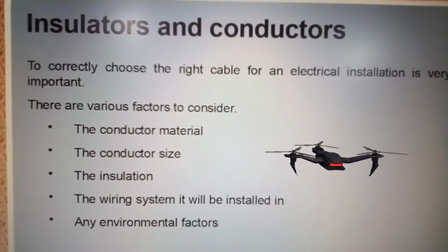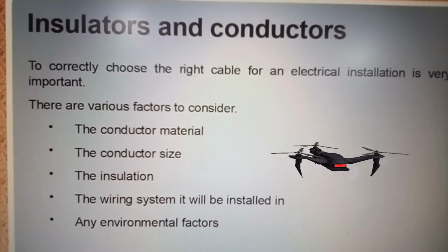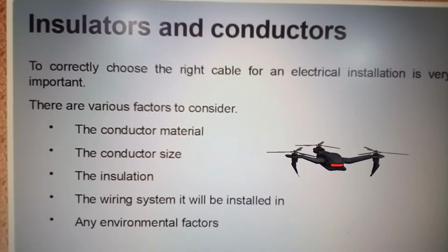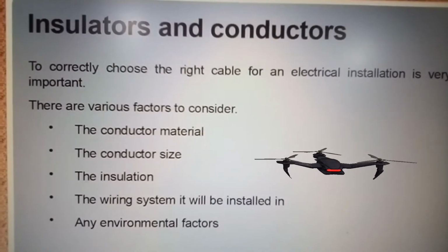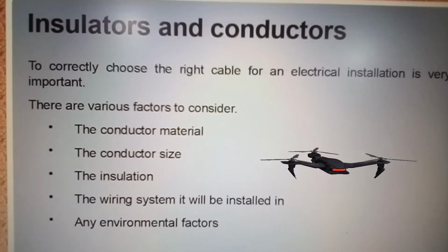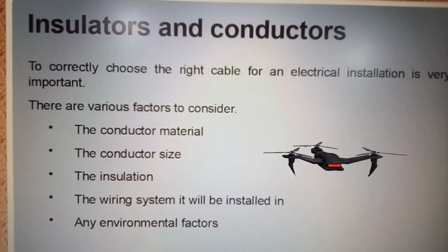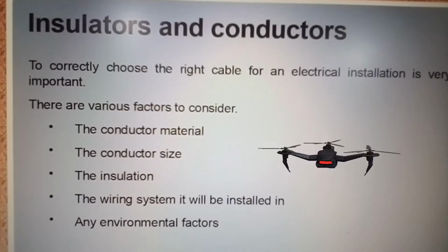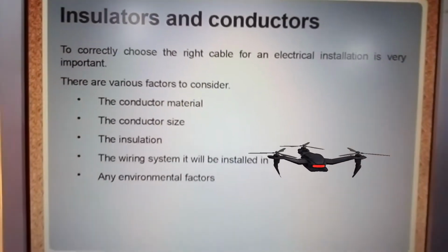To correctly choose the right cable for an electrical installation is very important. There are various factors to consider: the conductor material, the conductor size, the insulation, the wiring system it will be installed in, and any environmental factors. All this matters.